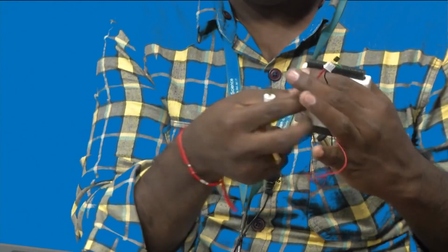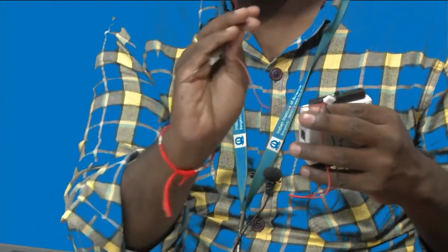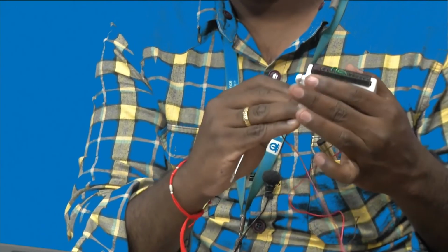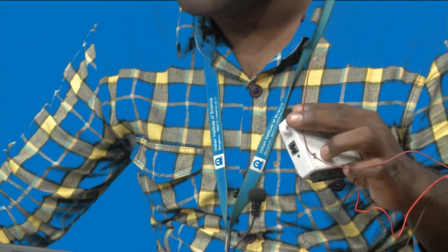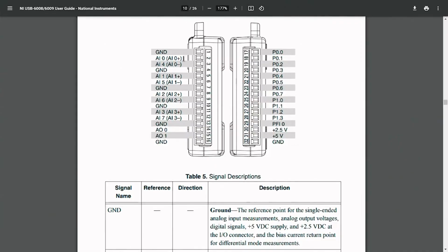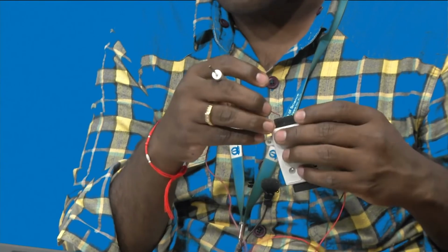Now the second pin, which is an output that gives an output in the range of 10 millivolts per degree centigrade, will be connected to the second terminal. The second terminal here is AI0 plus or AI0. So if we are using a single reference, as we discussed previously, since the grounds are common in this case, I will use a single reference. Then AI0, I will only connect it to AI0, that is the second pin.